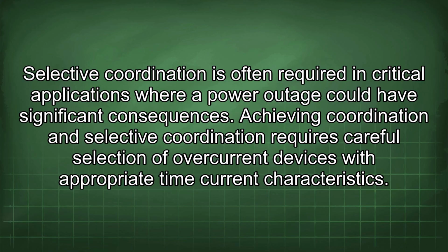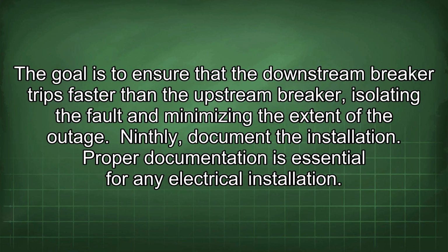Achieving coordination and selective coordination requires careful selection of overcurrent devices with appropriate time current characteristics. The goal is to ensure that the downstream breaker trips faster than the upstream breaker, isolating the fault and minimizing the extent of the outage.